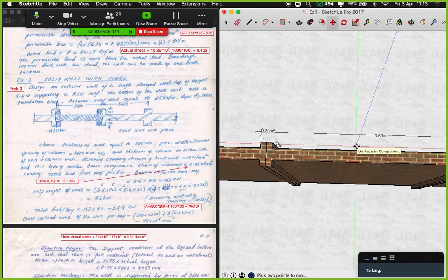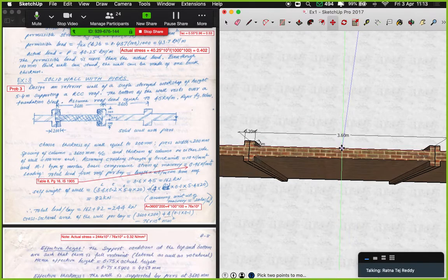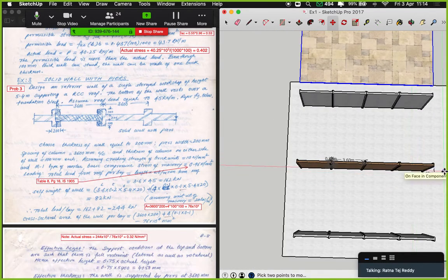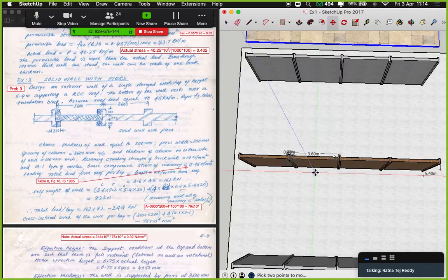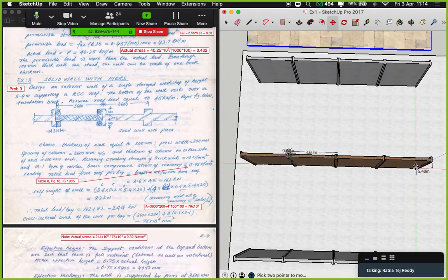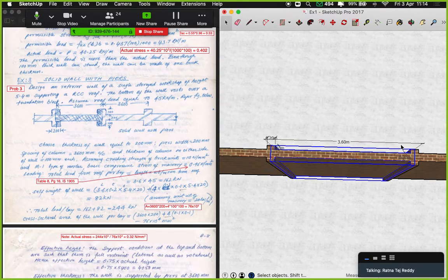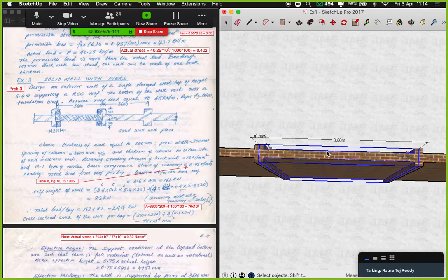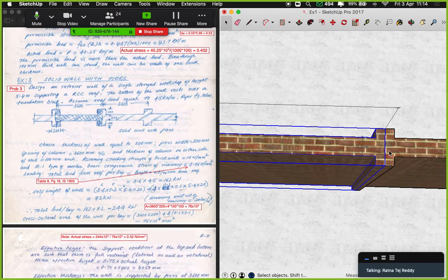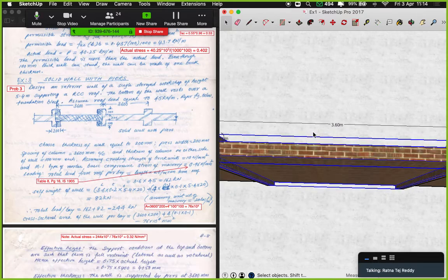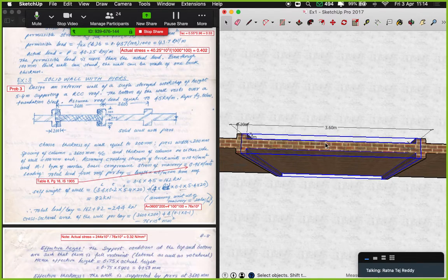the center to center of a bay. Now a bay is nothing but, see, in this particular structure we have 4 bays. I have just modeled 4 bays. They can be many, but for this particular structure there are 5 piers and 4 bays. Now each bay is enclosed between 2 piers, and the center to center distance from the pier to the next pier is the span of bay which we consider, which is 3.6 meters over here. So the exact center of the pier on either side, the distance between the exact centers of the piers will be 3.6 meters as given in the question.